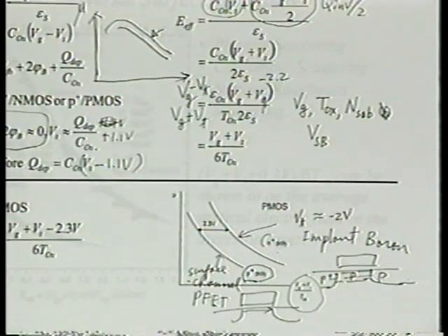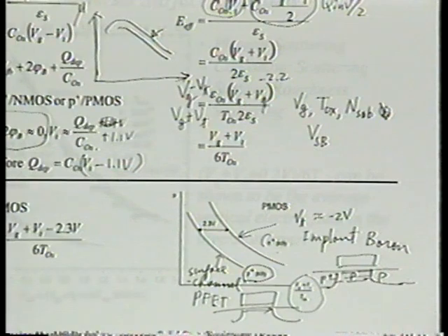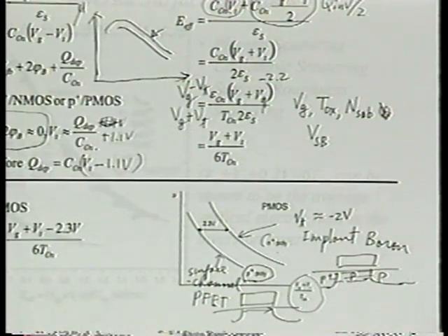And it will be very interesting for you to try to draw some energy diagrams and see if you can prove to yourself it has to be at the surface with the kind of voltage we're talking about. Yes? But the flicker noise of buried channel devices is consistently measured to be lower than surface channel devices. So I would like you to also try to explain that, maybe as a question we can discuss in the discussion hour later.